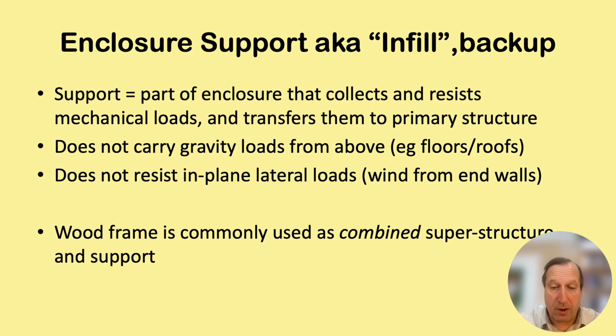Now again, I want to remind you that there is a significant category of building systems that combine enclosure and superstructure. One of the obvious ones is light wood framing. Load-bearing masonry in the historic past was always done this way. It is only in the modern world that the majority of larger commercial institutional buildings are separating out the enclosure support function from the building structure function.